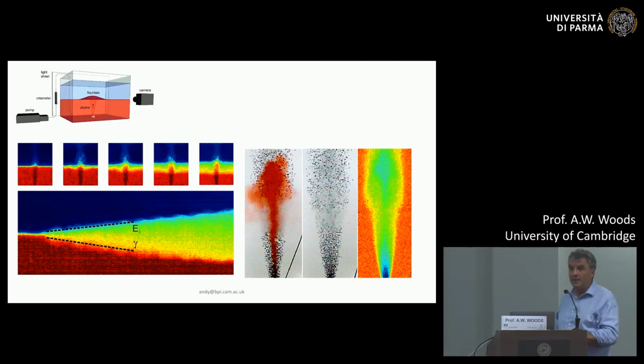And so if you're interested in mixing a water reservoir, which can get stratified in the summer, or you're interested in mixing lakes, I guess they've done experiments in Lake Geneva trying to mix up lakes. This is actually showing you what happens if the bubble plume doesn't bring fluid all the way to the surface, but actually mixes the interior. And it's very interesting just having a look at what's going on at an early stage at the interface. So here's the interface, and what we see is that the red fluid rises up, stops, and then it sinks back down again and spreads out.